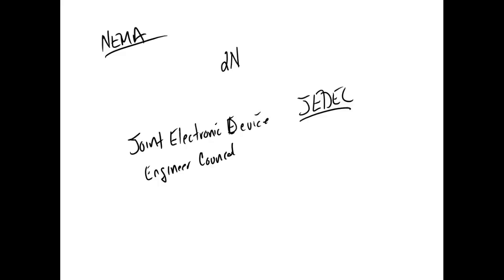So in electronic packaging, we started making transistors, and I'm trying to run a company that makes circuit boards. And this guy's got a package that there's no standard mask out there. So I have to get my engineers to come down there and make a mask. Well, if it was an open technology mask, odds are I can buy a CAD program like AutoCAD, and that layout with all the spacing and everything would be perfect, and all I have to do on my drawing is just pull it in. So JEDEC is the one that registers packages.